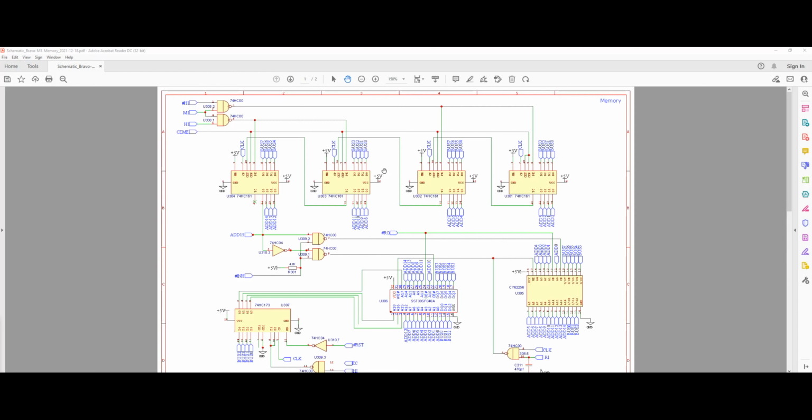Now you may ask why we have a memory address register here, why we have another 16-bit binary counter, and why we couldn't just use our program counter output to address the memory. If you're coming from a project like Ben Eater's 8-bit computer, that's probably a question here, because in that build we took the output of the program counter and directly used it to address our memory.